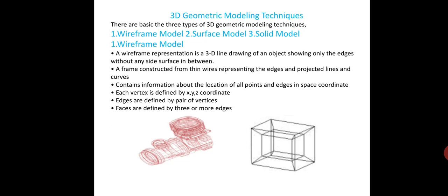Always there is a confusion where the line completes or where it intersects with other edges. Volume of the surface of the object is not defined. For a complex object, the result can be a jumble of lines that is impossible to determine. There is limited ability for checking interference between mating parts. There is no ability to determine computationally information such as the line of intersection between two faces of an intersecting model, and it cannot be used to calculate dynamic properties.